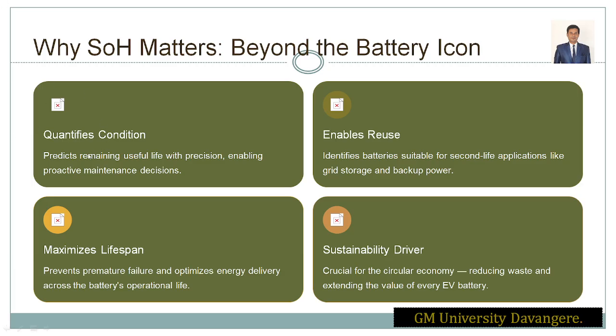So you can see there is a remaining useful life, right? For example, if SOH is around 82% and dropping 2% per year, right? Then the BMS will know, say for 1 year, 80% of SOH, and the remaining will just keep decreasing as the usage of the batteries happens, right? So in 1 year it was around 80% of SOH. If you see in 2 or 3 years, it will degrade to 70%, and then it will come to 65%, right?